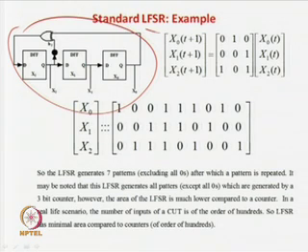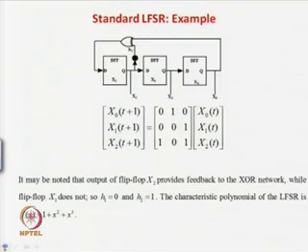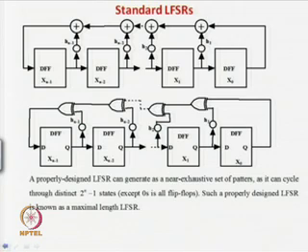In a standard LFSR, there is a chain of XOR gates. If there is another feedback from an XOR gate, you require another XOR gate over here; this input will be there and this will be feeding this, and so forth. So, the delay may increase in LFSRs because if you have a very high number of XOR gates, as you can see, if all these h's are 1, then 1, 2, 3, 4, up to n minus 1 2-input XOR gates will be there, feeding this one.